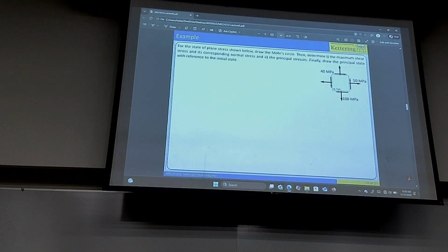So it's good that we're reviewing that. Reagan, I sympathize with you. That square root, it's not in square, is it? All right, point to you. Yes, square root of (sigma x minus sigma y) all over 2 squared plus tau xy squared. That's tau max. Olivia, please give us sigma max and sigma min equations.